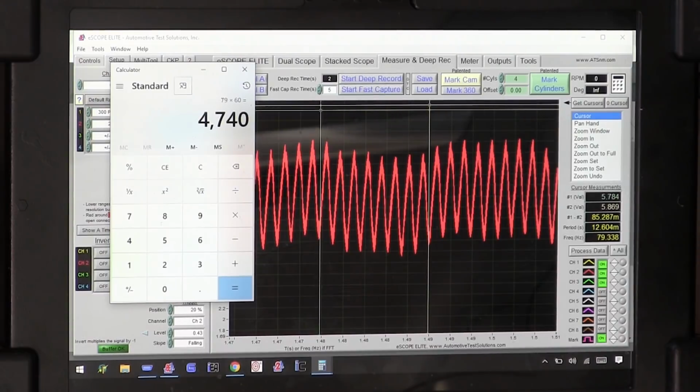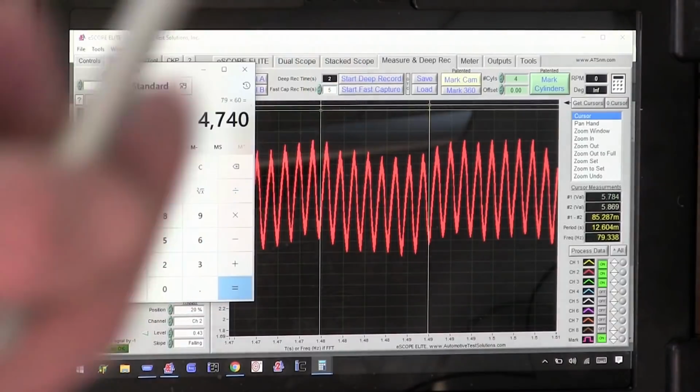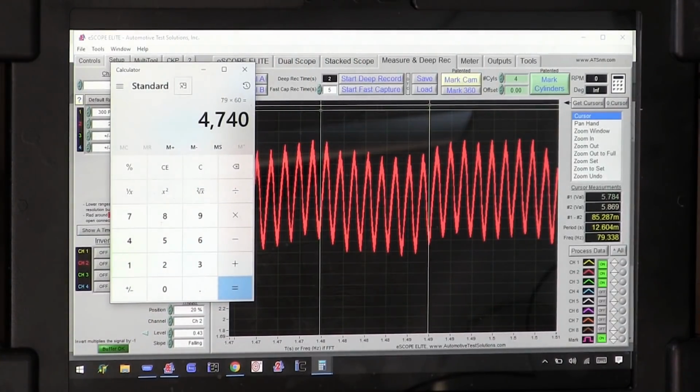Before you put a part in, test it. Get a scope. Get some data. Use data to drive your diagnostics rather than hanging parts. You're going to be way, way more successful using data. But right now I know what I've got to do. We're going to have to come back and get a lift and raise this car up, and then check that line to the front of the car. Somewhere from the top of the pump exit to the engine, that line is restricted.